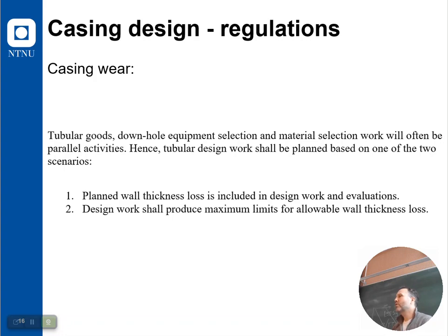You actually, for any casing, just simulating that okay, I'm going to drill this section, what is the wear? It's not going to work. What if at more or less the end of that section you get stuck? You have to cement back and you have to re-drill it, right? So you always need backup.